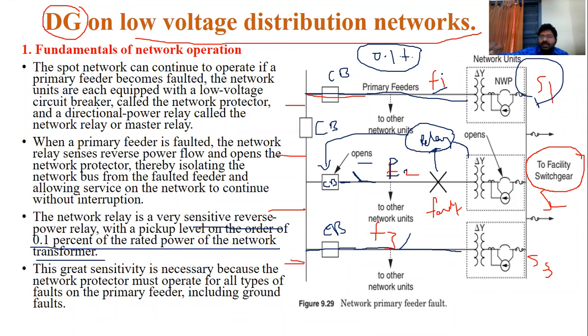Only if a plus or minus change of that percentage occurs in the system will the relay operate; otherwise the relay is not operated. By putting in lower values, the sensitivity of the relay increases, and it may cause some problems also.